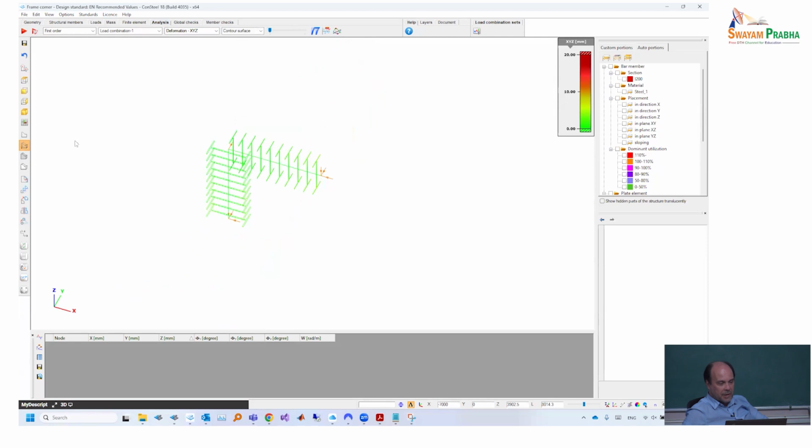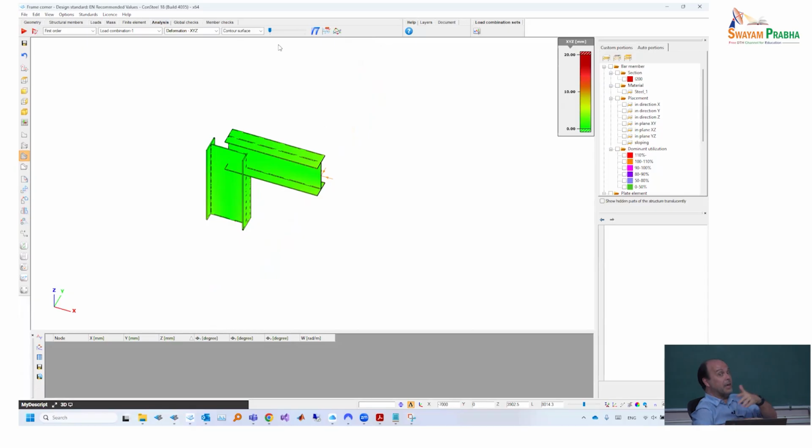Based on this, if no other information is available, we consider the warping transfer analogically to any other type of internal force transfer. Exactly the same way as we transfer a bending moment, we can mathematically do the same also with the warping.